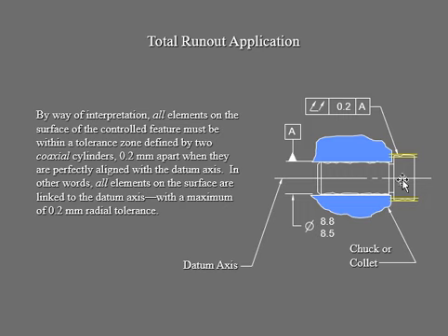When we say total, since we're always using the datum axis as our datum feature, your total is going to be on both sides of that axis. So that's what we're talking about. In circular, if you remember, we always showed only one surface, not both sides. So right now I show both sides, meaning go ahead and deal with this and that.